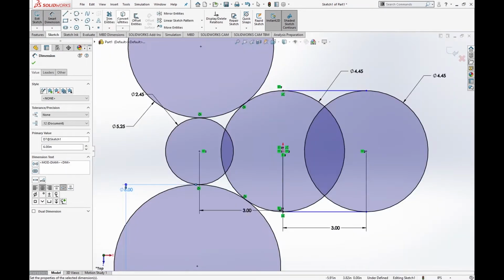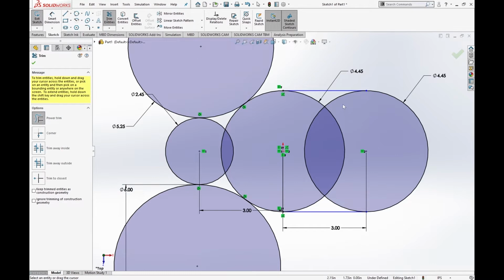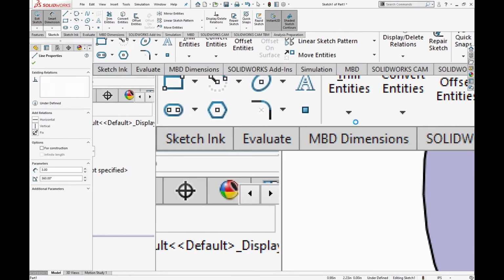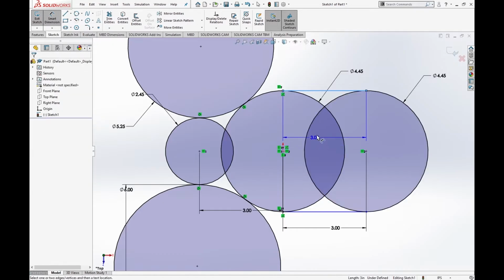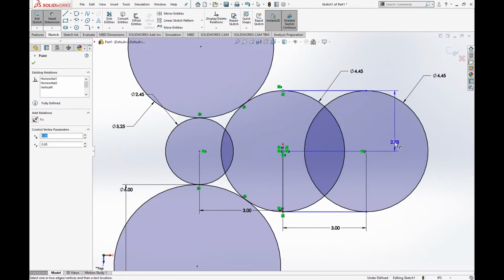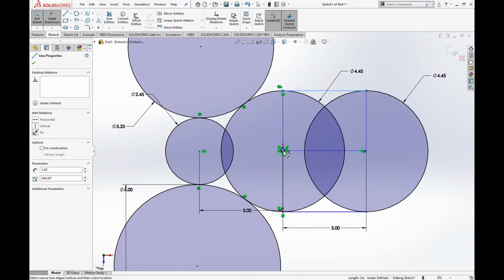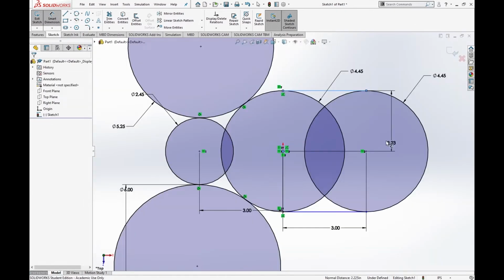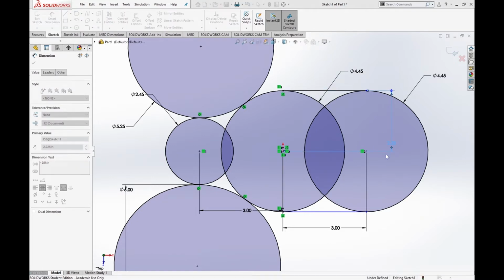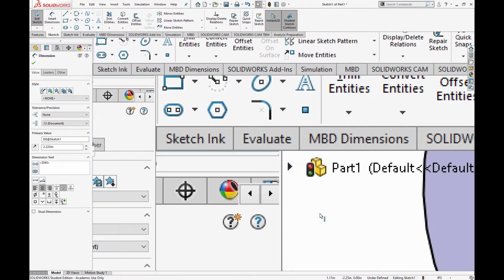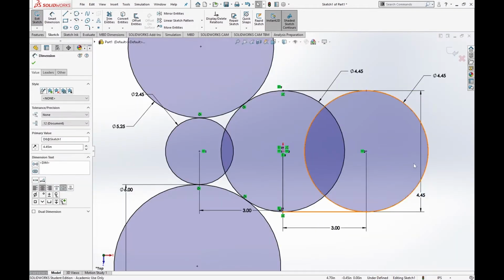And so now let's go ahead and start trimming stuff. I want to constrain this line, since it's still blue, to this point. Then let me do that. So here to here. Do the same to this. Sorry about that. Okay, that's fine. And I'm going to do this to this one. Sorry again for that.